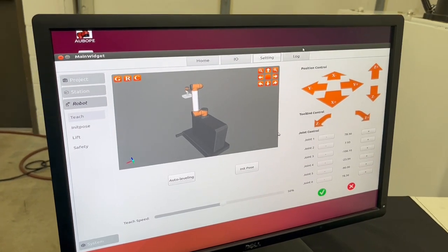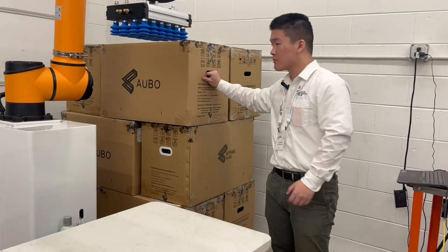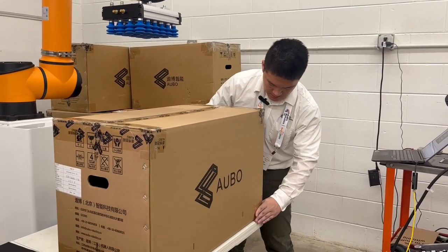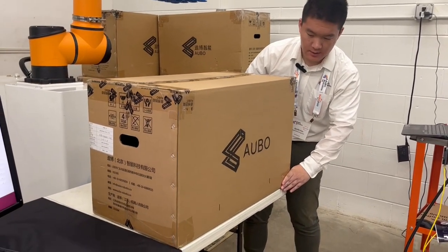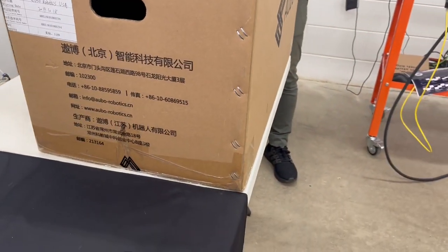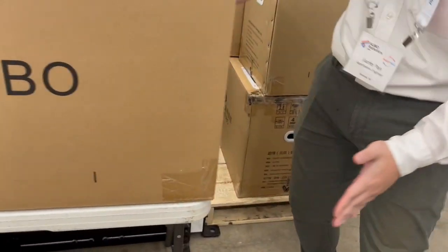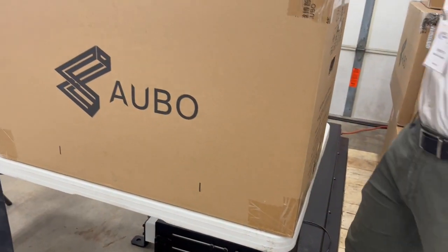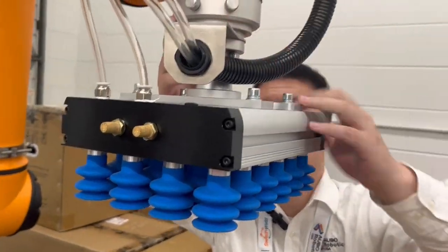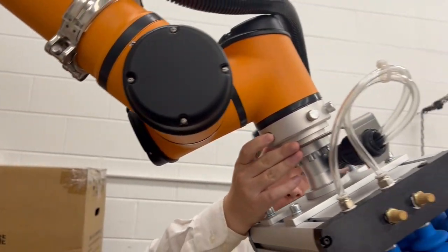To do that, I will use this box for calibration. So I put a box here, and I make sure the box is aligned properly, because in the actual production scenario, the box needs to be aligned at the exact same location. So this face facing here, that face facing here. Oh, there's a button at the back you can press and hold to move the robot around.